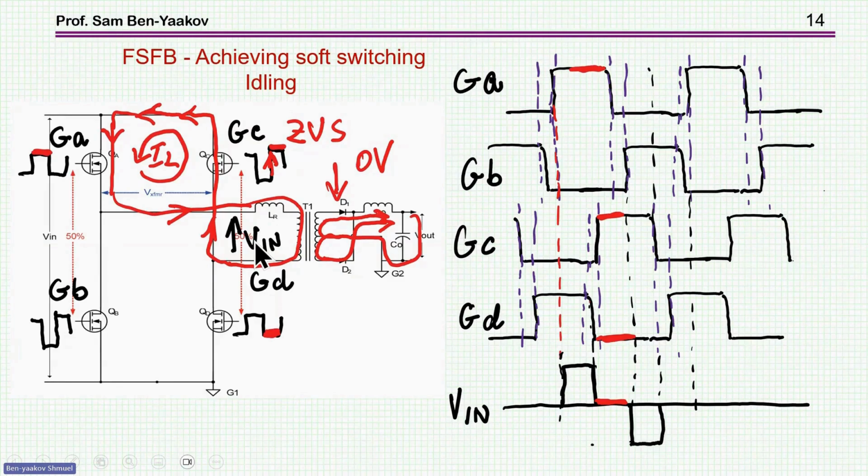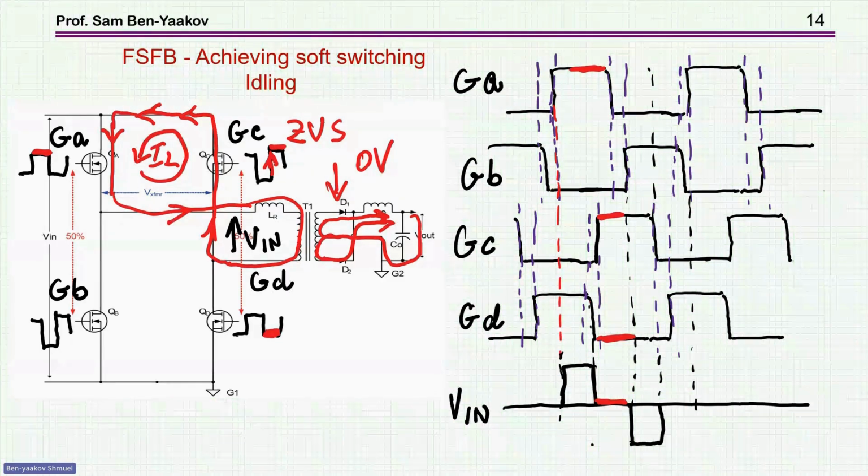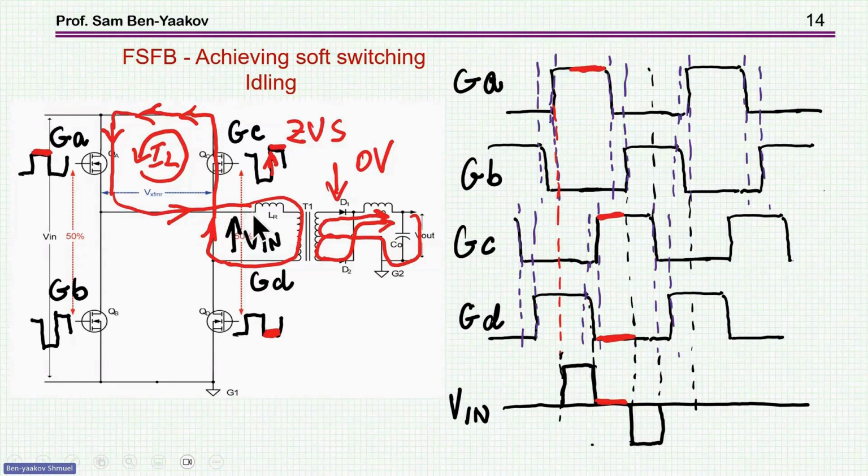Now, if you have an inductor which is shorted, the current theoretically will circulate indefinitely. However, due to the parasitic resistance of the inductor and the transistors, it'll start actually going down with a certain slope depending on the time constant. So you are losing some of the current, which is very important because of the next stage. You need this energy, as we'll see later on.